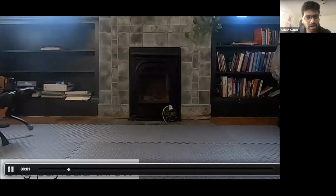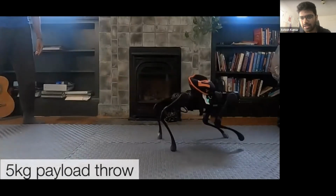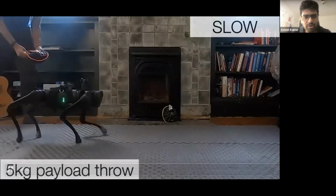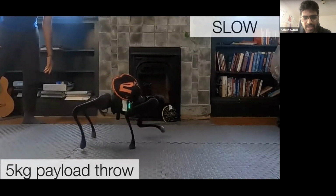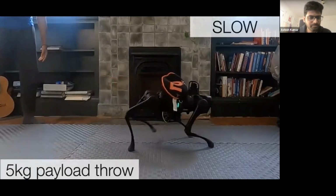We have another example, which is a payload throw. We can toss 5 kg of weight on the back of the robot, and we see that it gets disbalanced and then continues walking. We can see it in slow motion. You notice that when the payload lands on the back, the robot actually goes down, continues walking for a while, and then if you focus on the green dots, you'll see that it goes back up.